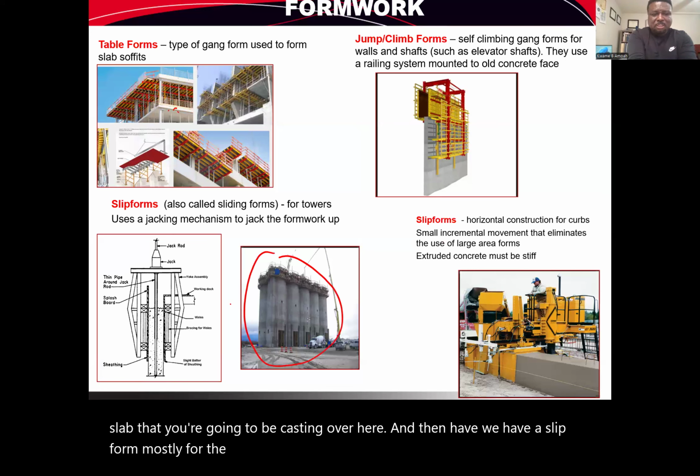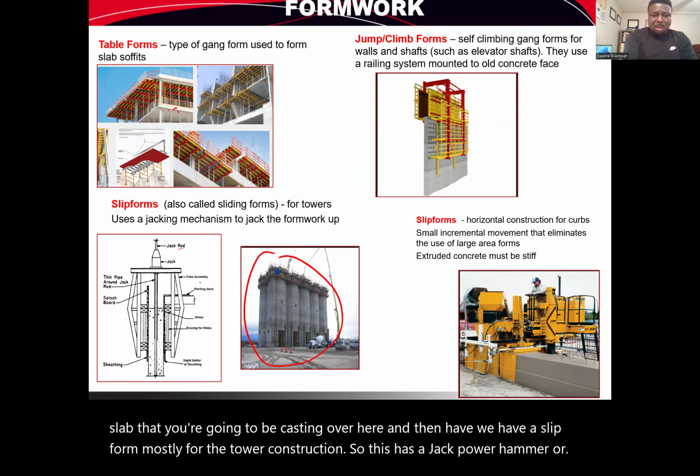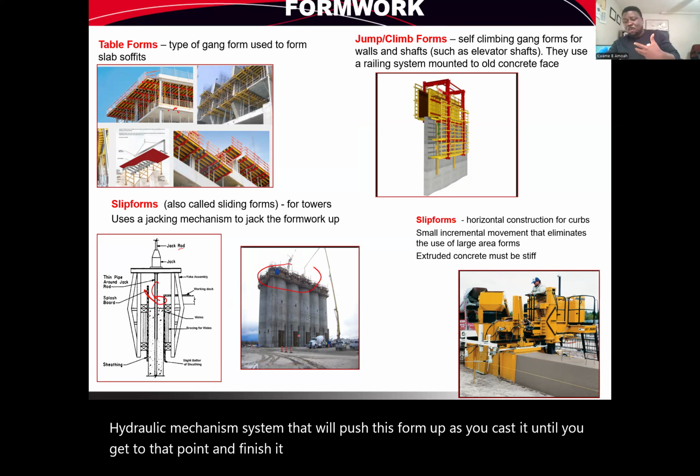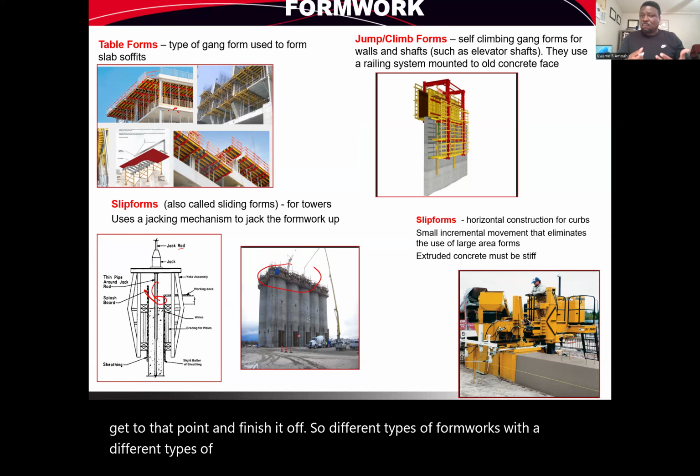So this has a jack or hydraulic mechanism system that will push this form up as you cast it until you get to that point and finish it off. So there are different types of formwork for different types of work, depending on which type of work you find in your project.